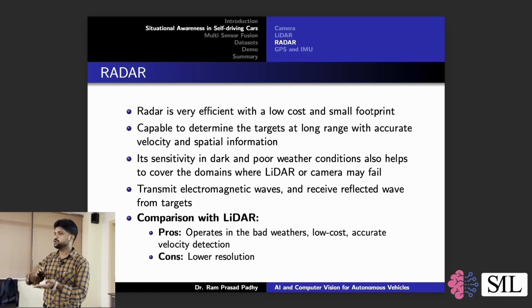At the same time, we should know their kinematics parameters, right? Velocity and acceleration and everything. So that is where the radar comes into the picture, and you will see that at some point we have to do the fusion between radar and LiDAR, because LiDAR will give you what kind of object it is and radar will tell you the velocity of those objects.